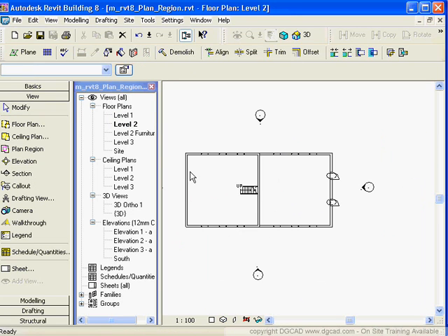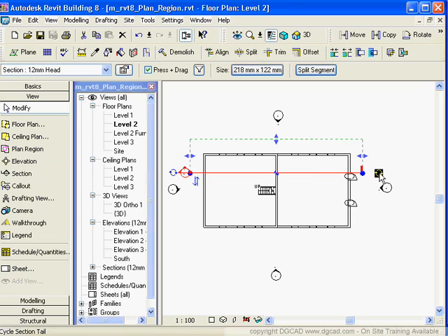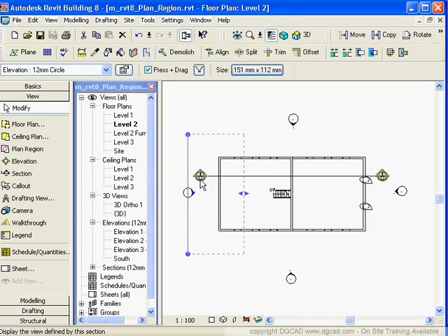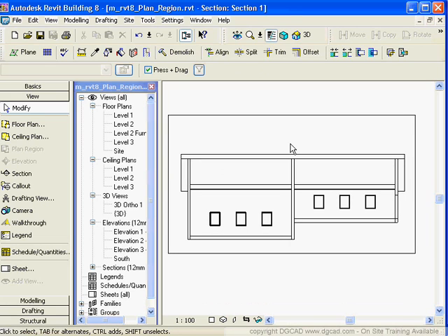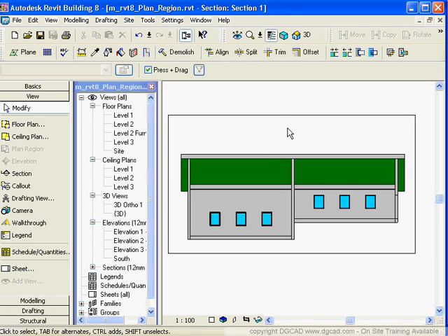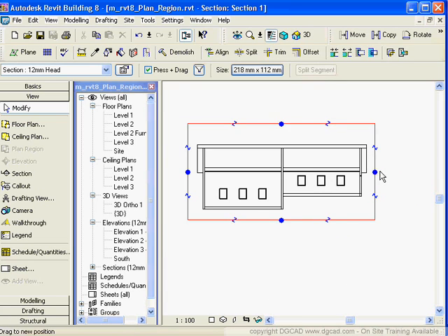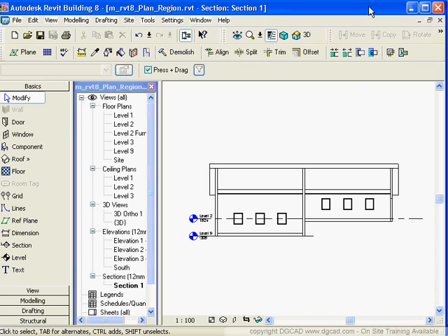So going back now, we just kind of move along to doing a section again. Level 1 doesn't matter, level 2, and this section is a 3D object, so we can just drag and place it, click it inside of there. If we want the section bubble over here, we can click on this and get the section bubble if we want them on both. Double clicking on this part of the bubble will bring you to that actual section. Again, shaded, maybe hidden line. Okay, we can move this back and forth.